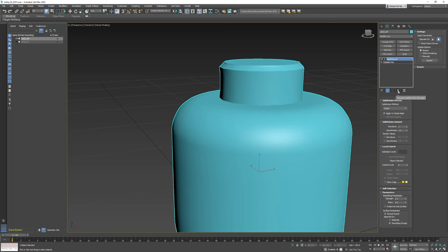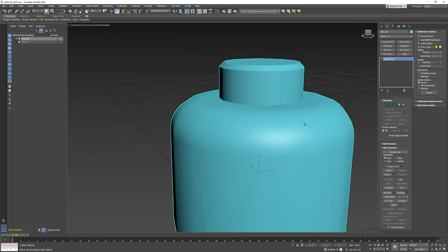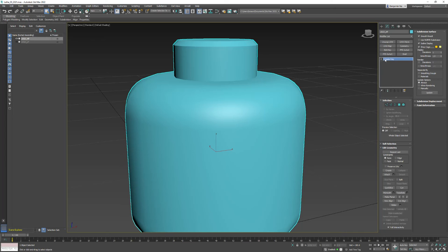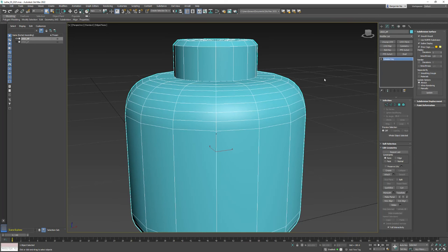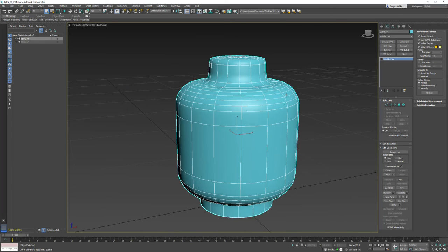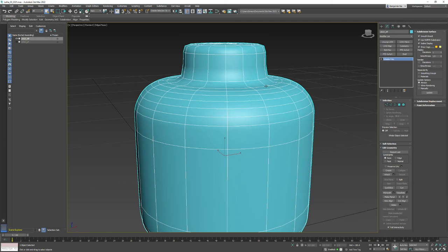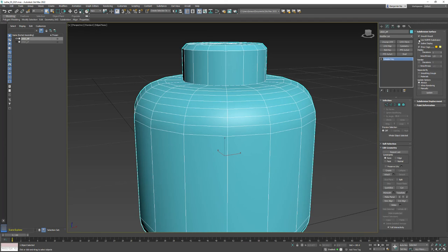So before you go in and try anything like just putting a mesh smooth on, there's another option where if you're at the edit poly, that's the bottommost component of your mesh, there's a rollout here called subdivision surfaces that shows up. And so if I come into use NURMS subdivision and I check that, I see my mesh smoothed out. Anytime you have that on, you want to make sure that you don't right click and convert to edit poly, because that'll make what you've done to your mesh permanent, in which case it's going to double the amount of polygons. Really the thing I want to talk about primarily though, beyond all that, is just how do we keep this from turning to mush?